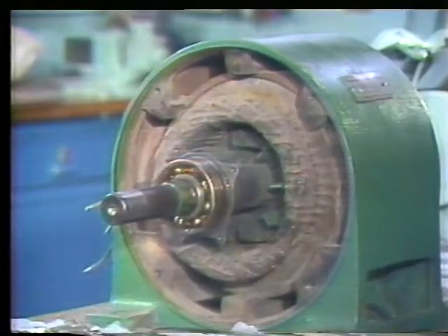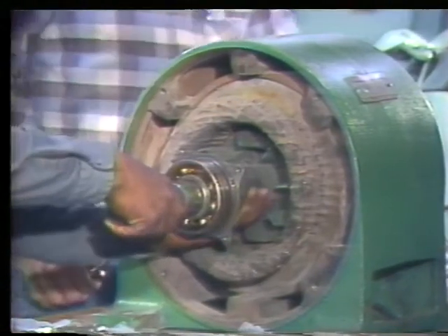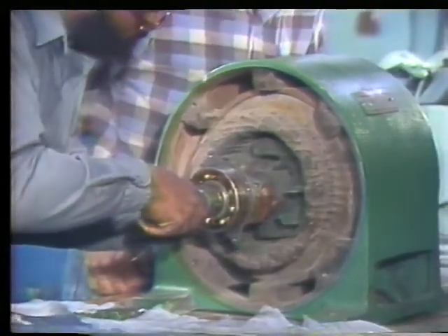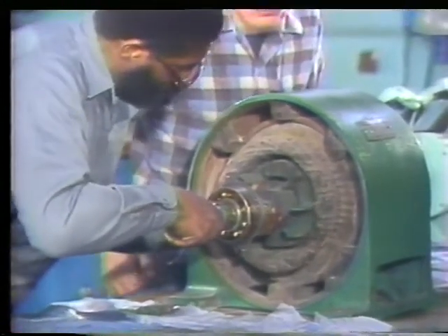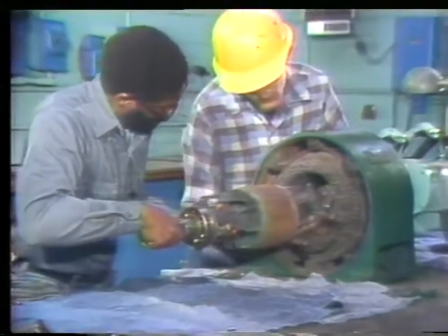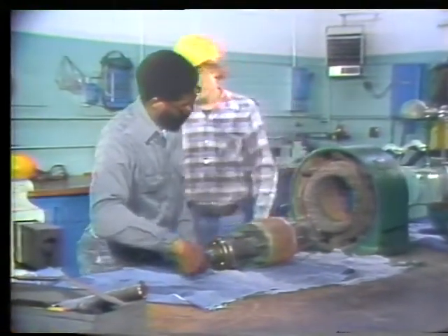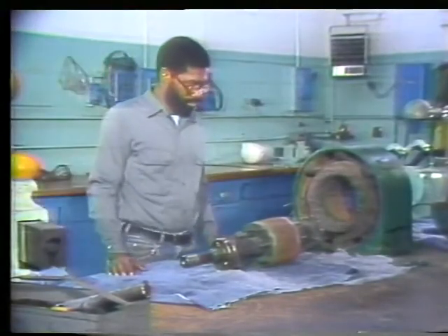Now, the rotor can be lifted out of the motor. The rotor may be too heavy for you to lift by yourself, so don't hesitate to ask someone to help you. Lift the rotor from the motor and lay it on the V-blocks or cloth. Don't drag the rotor across the stator poles. Dragging it could damage it and the stator. The motor is now disassembled and ready for inspection.